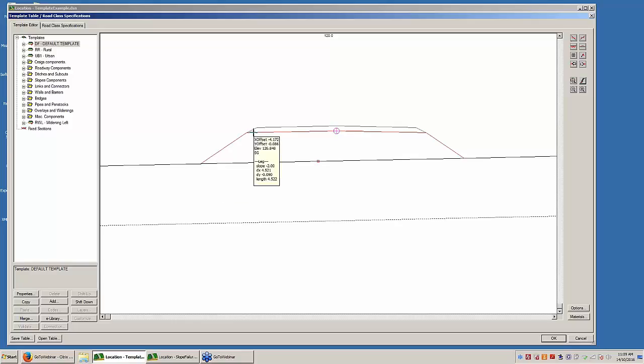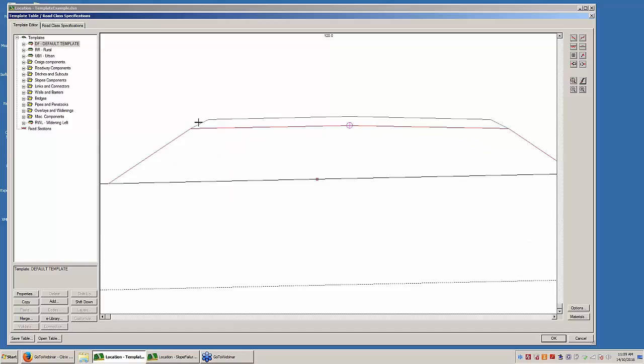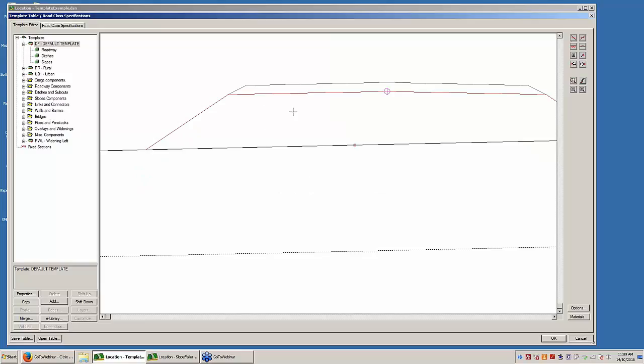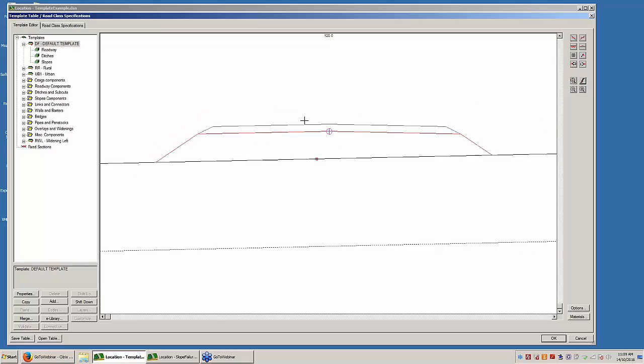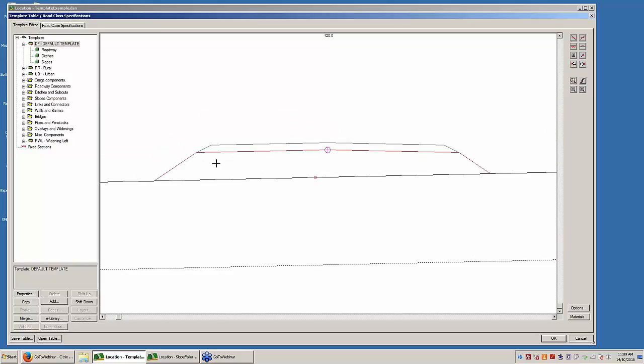And here is the same. The whole subgrade surface is displayed in red. And then above that I have another surface, and that's called SRF1. And those are defined by the components of the template. And those surfaces actually define areas. So in here, anything below this subgrade surface, when I hover, I get a fill, subgrade fill. Anything below that surface tells me it's subgrade fill.